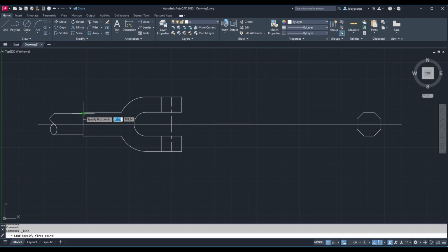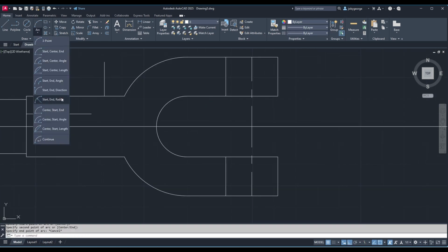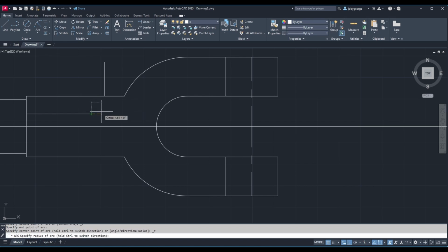so I know that this is at a distance of 36. Okay, so from there I will use the track option, then I will type 36, then I will put my line like this to get an idea of this. Then I will use the cut and radius curve. So note this. From bottom start, then end, then use some radius. Okay. So I will delete this.